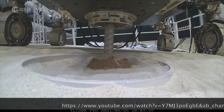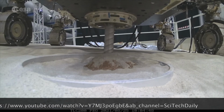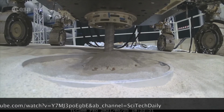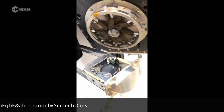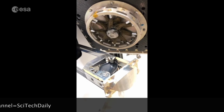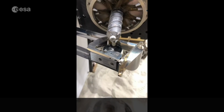Only the first rod has a volume to retrieve the samples. When the first rod is fully underground, it disconnects from the mandrel and the next extension rod is placed in between. After the samples are acquired, the drill string is lifted out of the ground and disassembled.